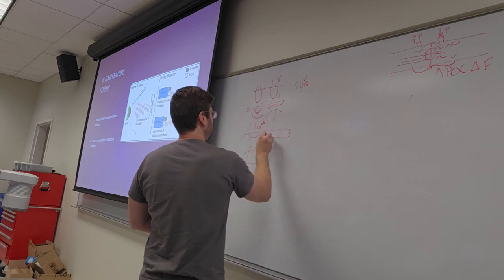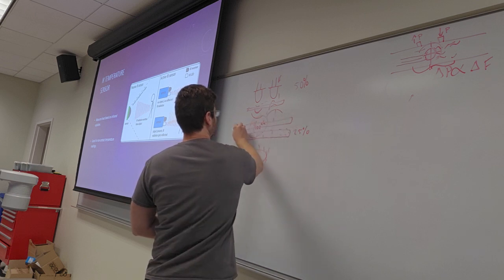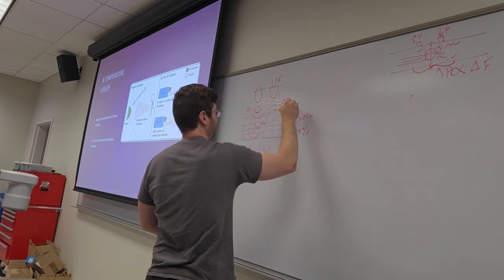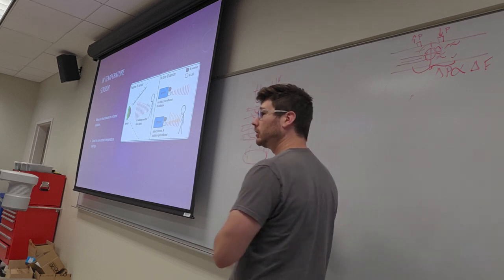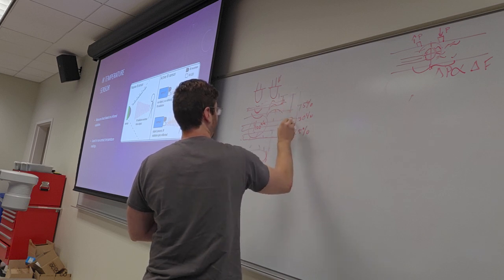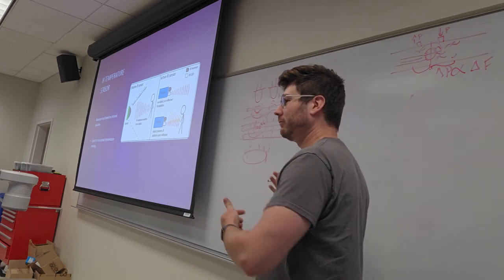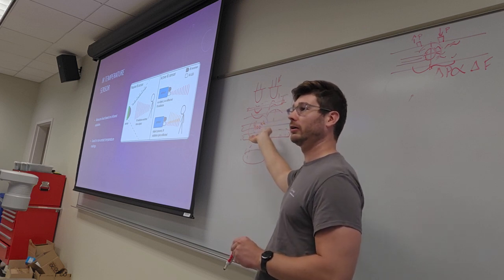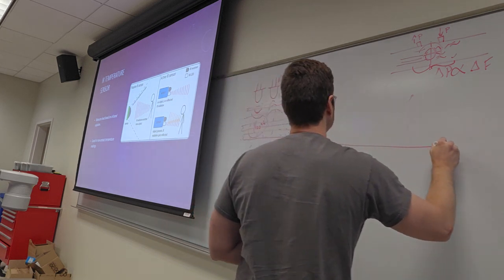If something is here, we will receive 25% of the light back. If something is here, we'll get 50%, right? Here we'll get 75%, something coarse like that. Okay, so you guys have seen here that we made a really simple distance sensor. We can tell if something is this far, this far, this far, or this far, or nothing's there at all. Effectively, you guys can probably pretty easily see how you could make a soap dispenser or something that would trigger with this. The interesting part though is that this is an analog design.